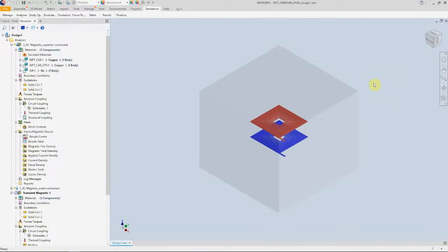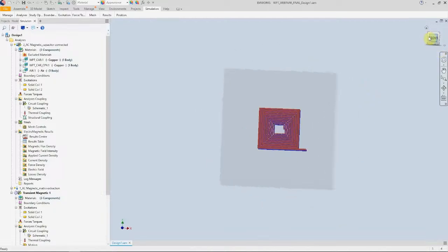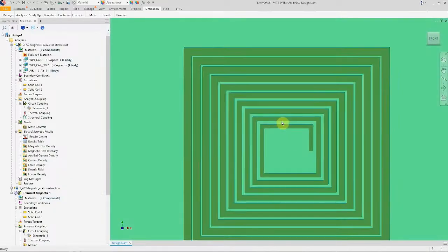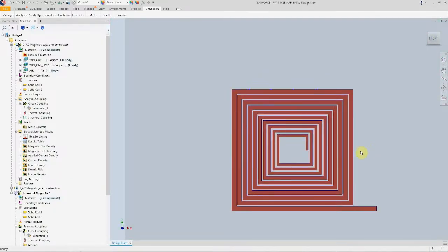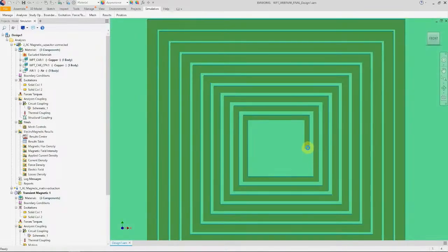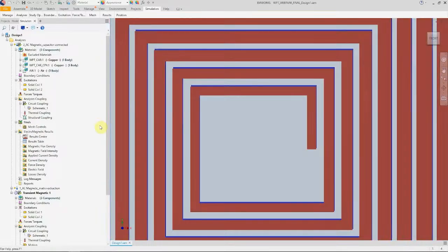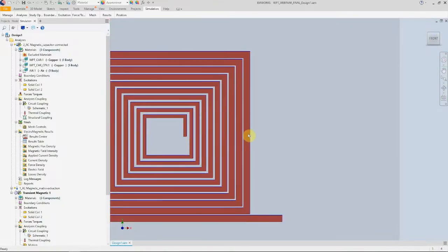In this webinar, we just show some practical points like why we selected the conductor widths differently when they get near to the center. You can see the wire diameter or width of the wire in the center is smaller than the wires at the edges. The distance between the wires can be a parameter to modify the quality factor too.